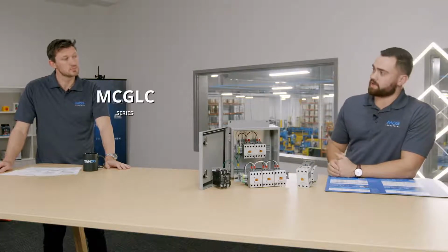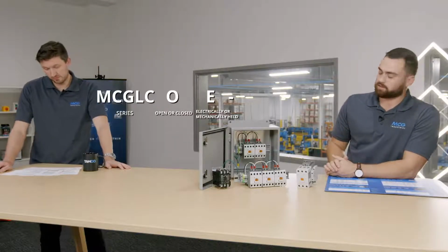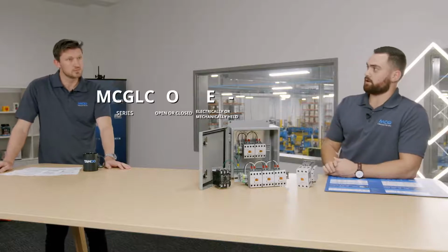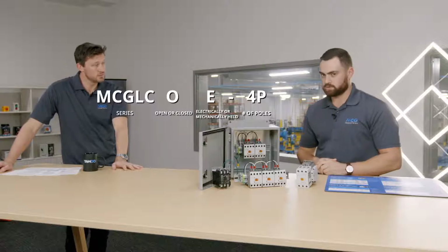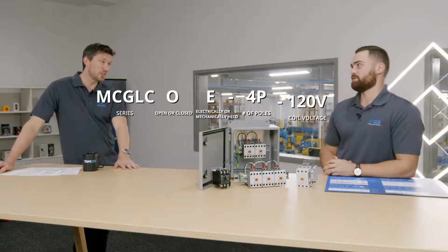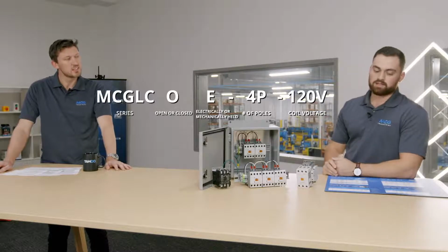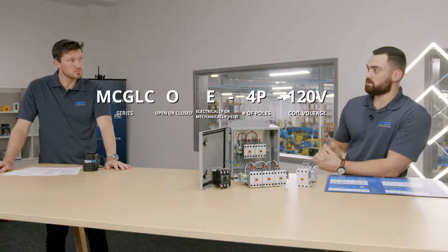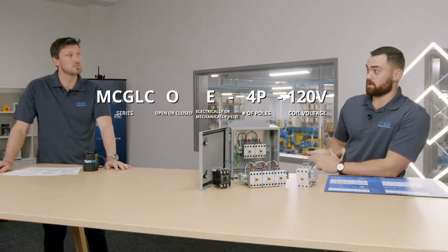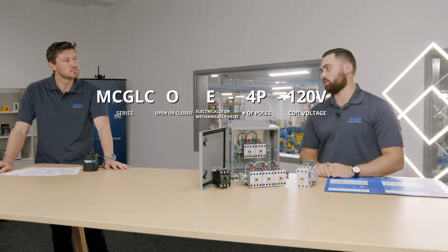Now, the first question I have to ask you is, is this lighting contactor going to be enclosed or open? Open. Open? Okay, great. And secondly, do you want this electronically or mechanically held? Electronically, please. Electronically, awesome. And the number of poles? 4 poles. 4 poles. And lastly, the coil voltage? 120 volt. 120, awesome. So the part number that you need, Anthony, for your customer is going to be MCG LC OE 4P, again, that's for your 4 pole, right? And then lastly, 120 volt for the 120 volt coil you need.